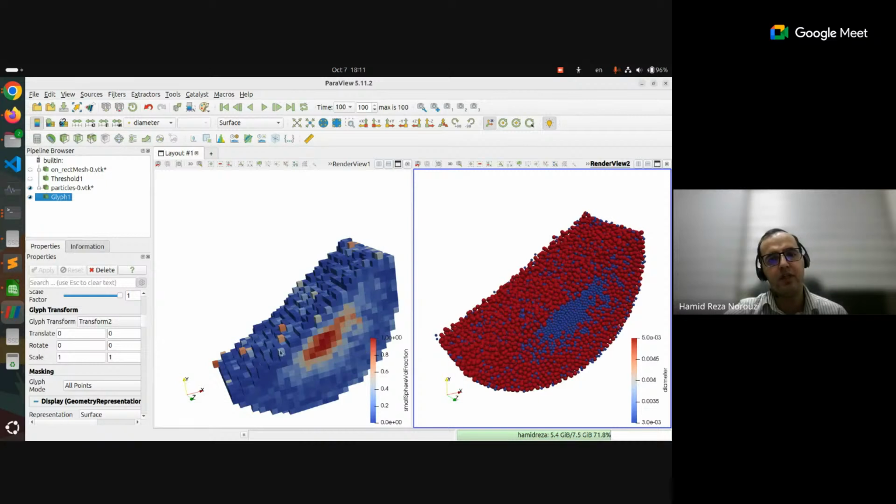And you see the post-process results on the concentration of the small particles. And using the volumetric concentration of the particles, you can calculate the Lacey mixing index and other mixing indices that you have in your project. Okay, that's all.